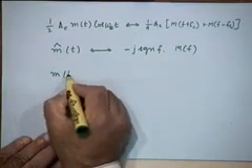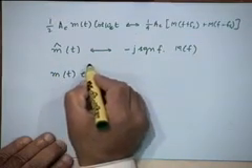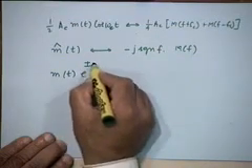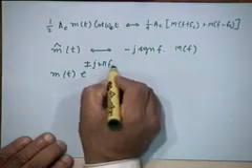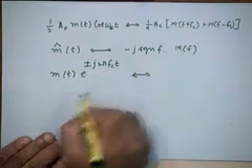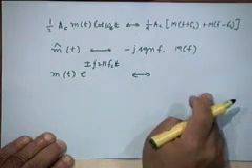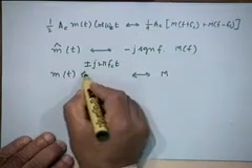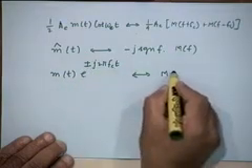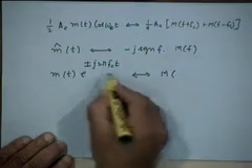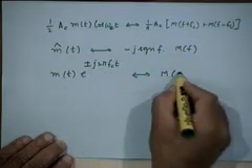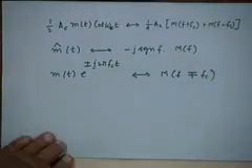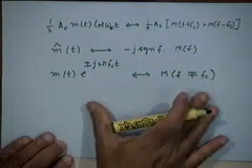Now also recollect the basic frequency translation theorem. Suppose you multiply mt with e to the power plus minus j2 pi fct, right? What is the corresponding frequency domain relation? When it is plus e to the power j2 pi fct, this will be f minus fc. When it is minus, it will be f plus fc. So this is f minus plus fc. Right? This is your basic frequency translation theorem.